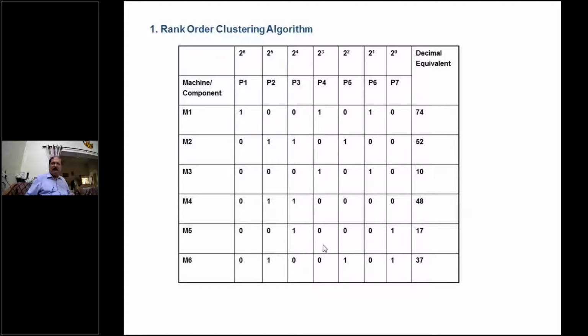For example, suppose there are 7 parts, P1, P2, P3, P4, P5, P6, P7, and the machines are M1, M2, M3, 6 machines are there. Now you see here, part 1 is visiting only machine 1, so only one operation is needed for part 1, on machine 1.